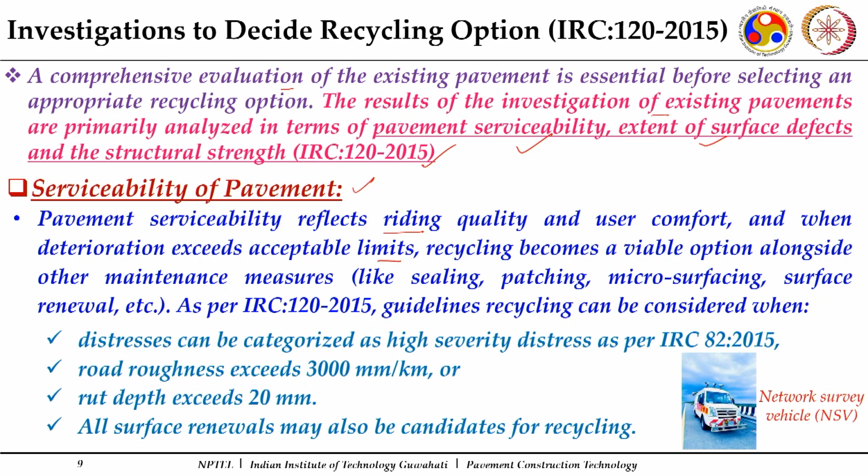Now, in addition to other maintenance activities which we have already discussed when we discussed IRC 82:2015, there are different kinds of maintenance treatments which are possible. If these distresses extend beyond a certain limit, recycling becomes a viable option. As per IRC 120:2015, recycling can be considered when the distresses come under the category of high severity as per IRC 82.